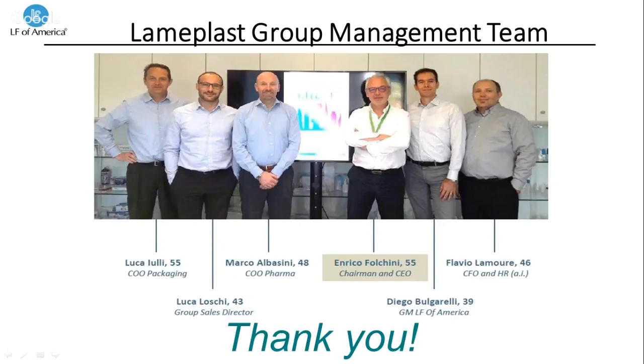Then, of course, you have to consider the startup and the setup process every time that you start a new production. So you have a different product than before. You have a different filling range. You have probably different sealing parameters in terms of temperature and timing. So I would say half an hour for the easier machine, up to 1 hour for the most complicated machine, but no more than that.